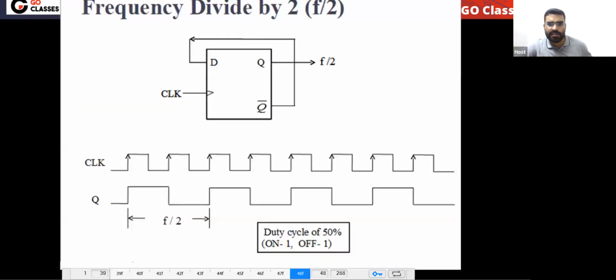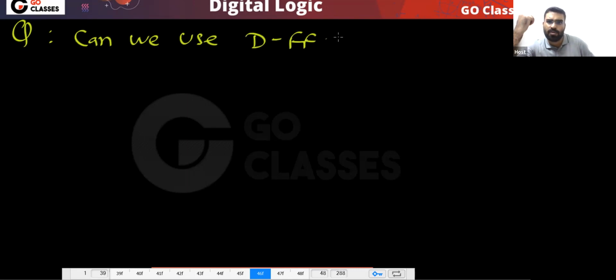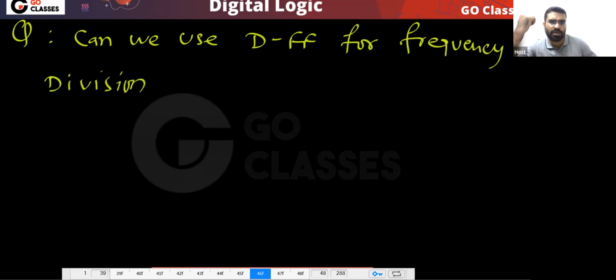Now tell me, can I use D flip-flop for frequency division? Yes, we can use it. But remember, we will use it as a T. This interesting point is coming: can we use D flip-flop for frequency division? The answer will be yes.